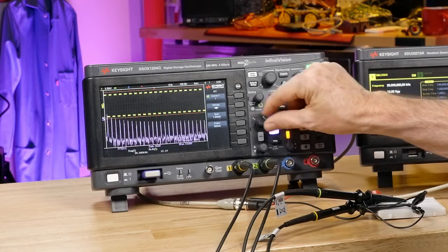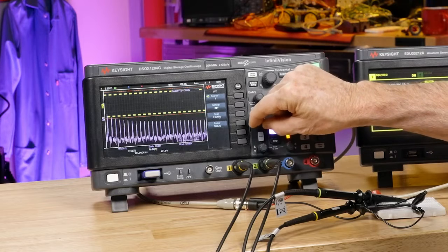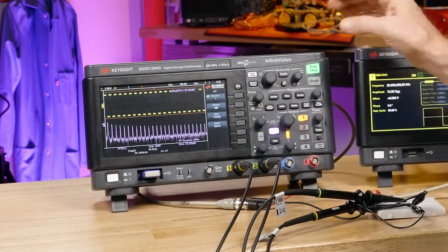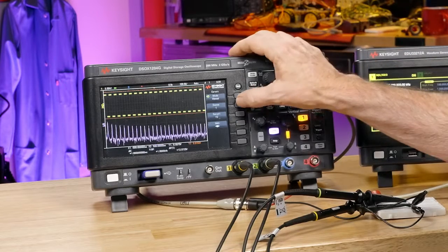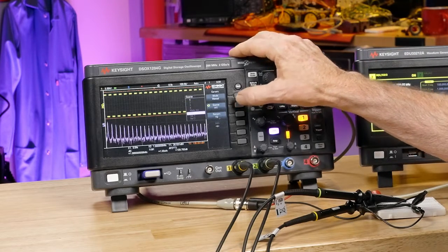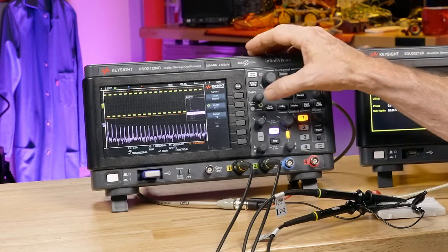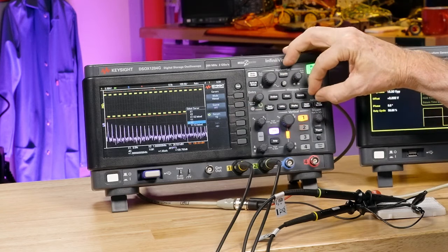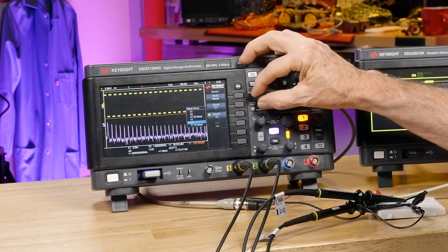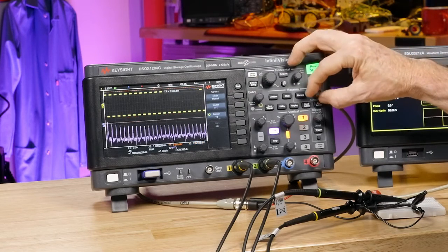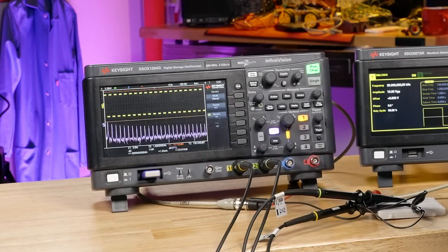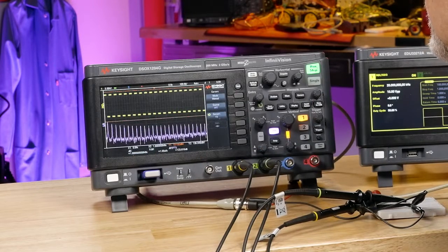Let's rescale this down a little bit so we can see it more clearly. We could turn on the cursors, select FFT, and then I could select the Y1 cursor and position it at the top of the fundamental, and it's measuring